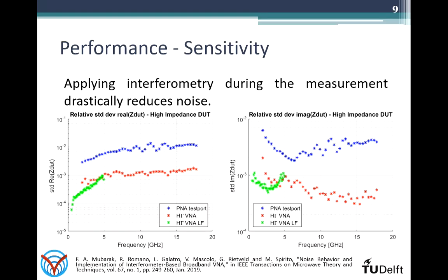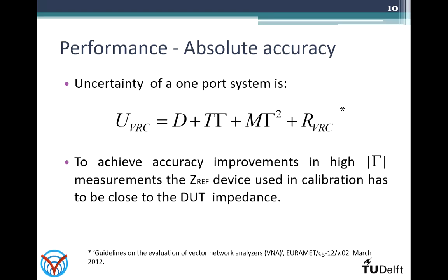But of course, this is not helping in improving the accuracy of our measurement. The accuracy of the measurement depends, in fact, on the calibration, and more in detail depends on the reference impedance we use as a load during the calibration.